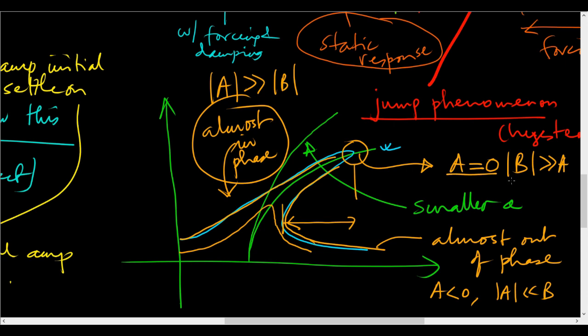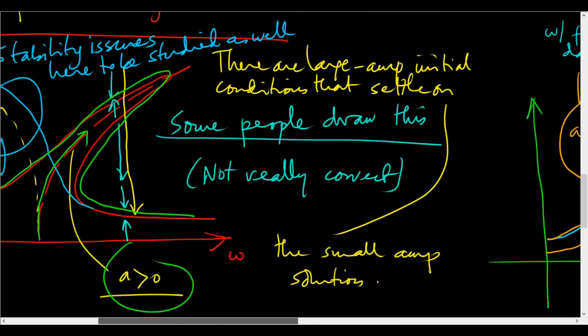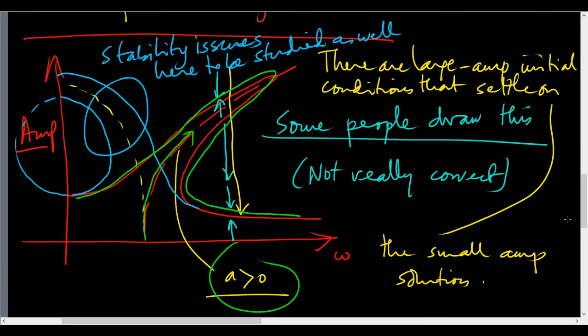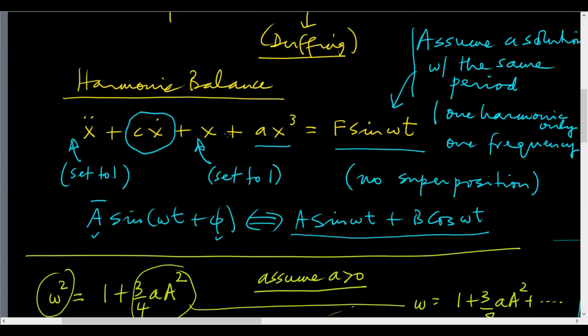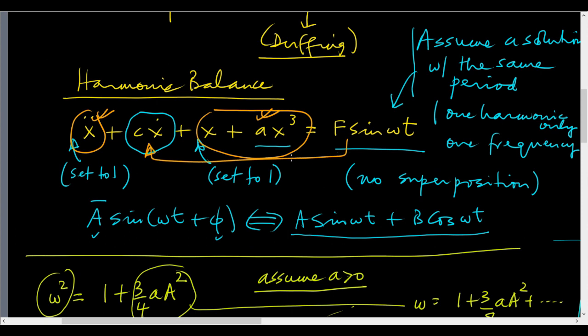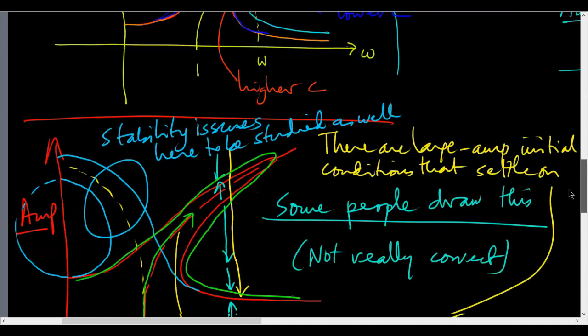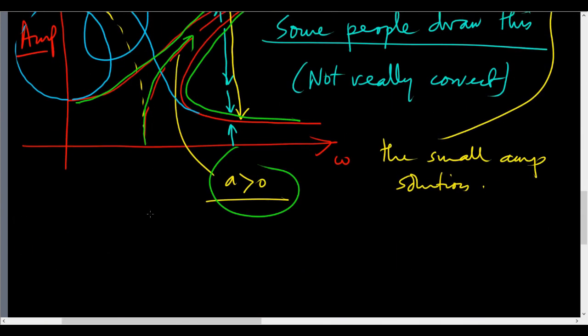Okay, then in the original equation, if you understand the energetics of the undamped linear oscillator, you will understand this part and this part cancel, and this part and this part exchange. So all the energy from here goes into here. That's the point of strongest response. That's the resonance.